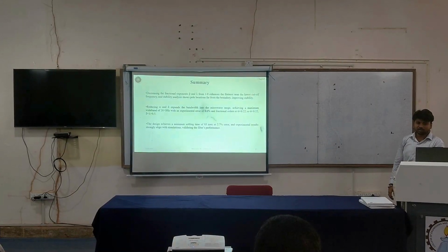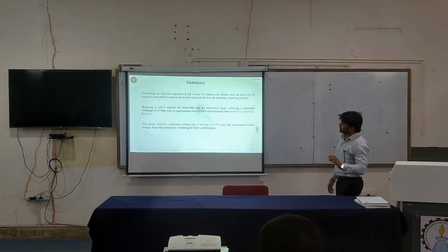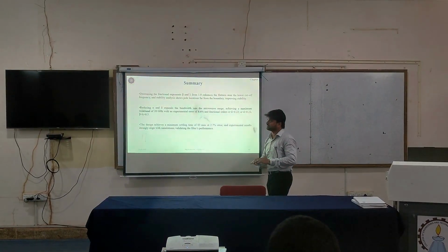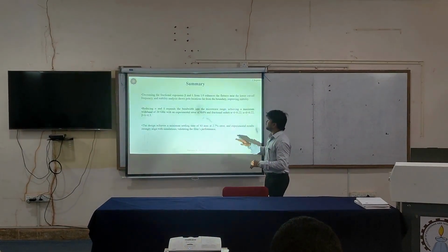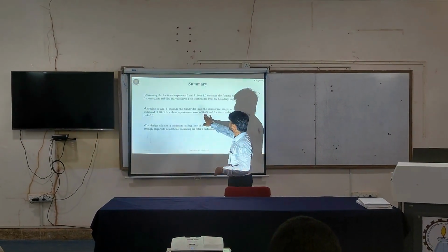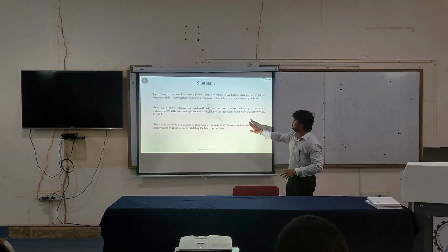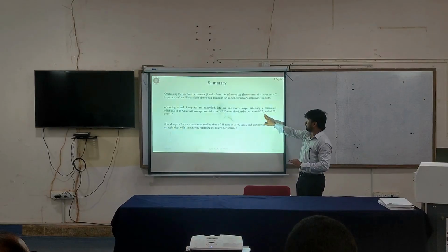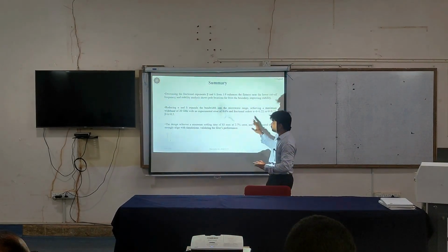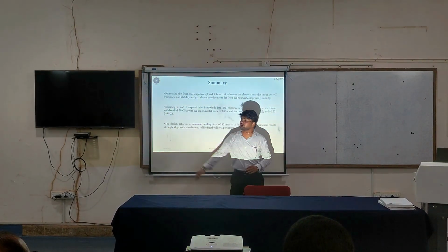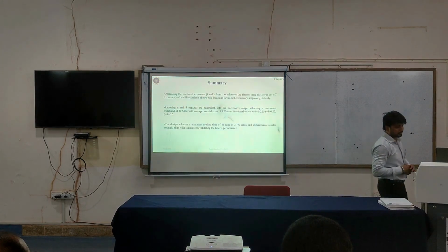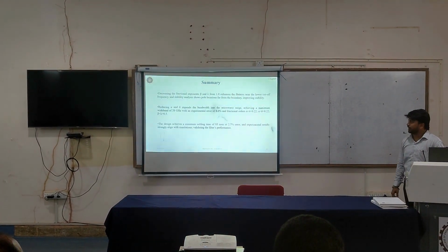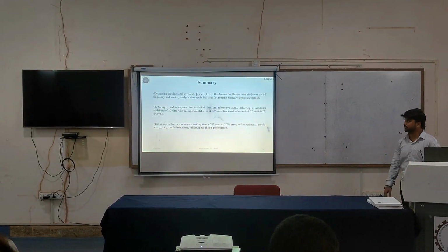Now coming on to the summary part. Decreasing the fractional exponents beta and lambda from 1.0 enhances the flatness near the lower cutoff frequency. It gives us a very high bandwidth at an error percent of 8.6%. Using fractional orders alpha equals delta equals 0.22 and beta equals lambda equals 0.5, this achieves a minimum settling time of 83 nanoseconds at an error percent of 2.7%.